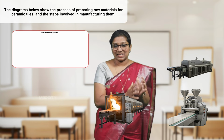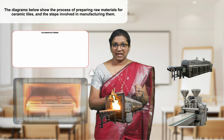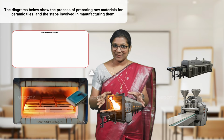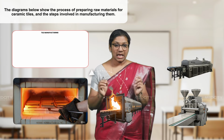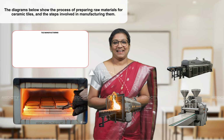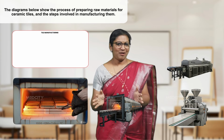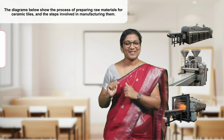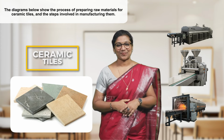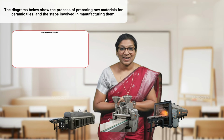So this glazed tile that we have here, which we've just done using the glazing machine, is put in the kiln for 20 to 30 minutes, and the temperature is 1000 degrees to 1250 degrees. It's very hot. And as it is subjected to this heat, after half an hour's time, we have our ceramic tiles ready. So here go our ceramic tiles. Now that we've understood the entire process, let's try and draft them.